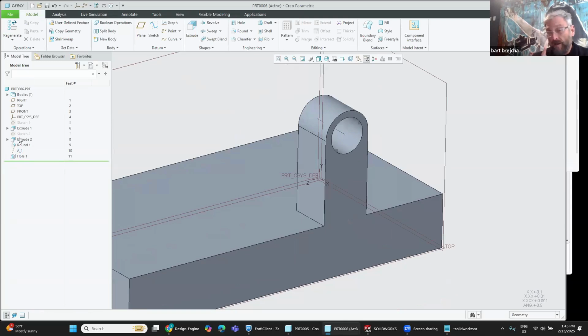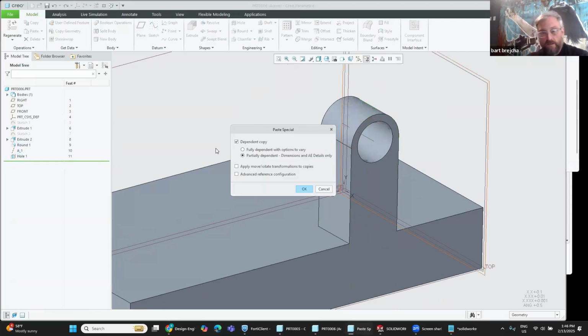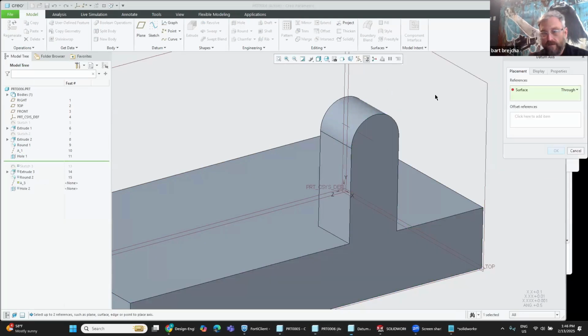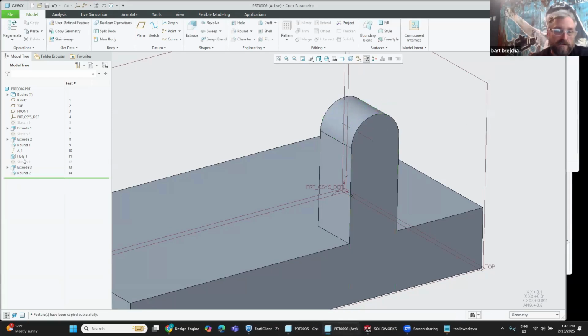This one's going to fail at the axis. The challenge for my thinking process is to guess where it might fail. And if you can duplicate a failure in a very specific way like that, there's something to learn from that. Now we can come up with a different way to do it. Control C, Control Shift V, right? I'm trying to do the same thing each time. Middle click, middle click. Okay. And look, it in fact fails exactly where I thought it might. It doesn't know how to organize to the top of the cylindrical wall. SolidWorks can't do anything like this.